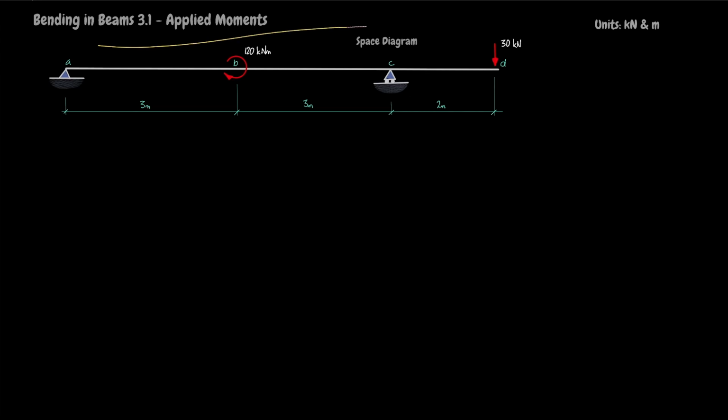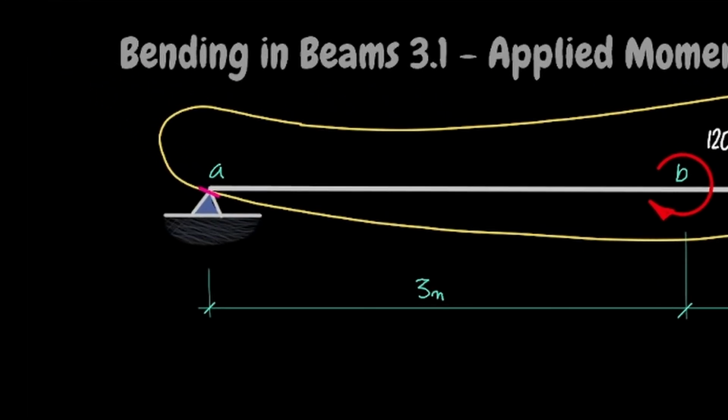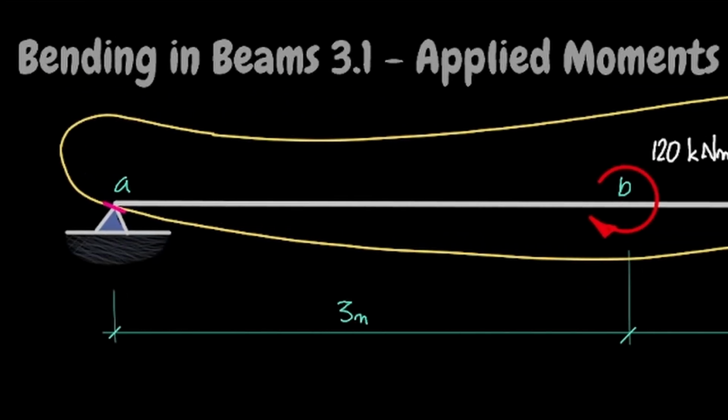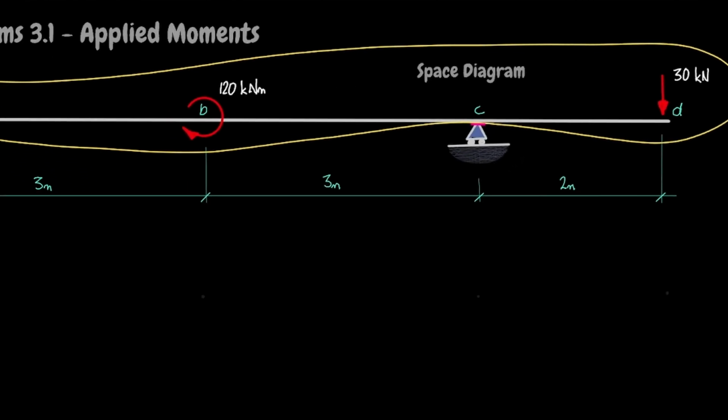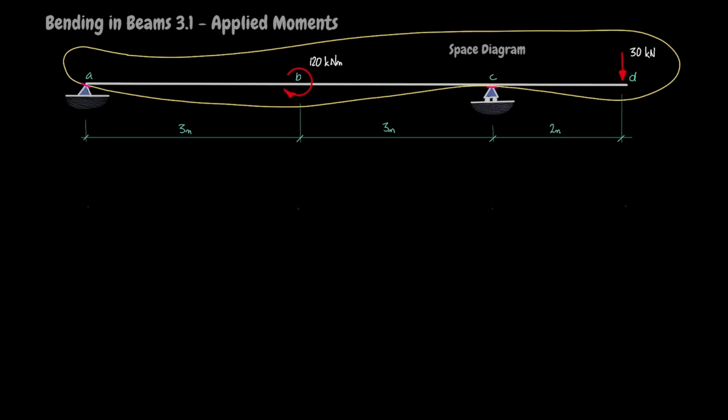Draw a free body diagram bubble that cuts the beam away from its supports. The purple lines represent cuts that will expose the unknown reactive forces. If this makes little sense to you, click the link on the screen to find out more about cuts, free body diagrams, bubbles, and all sorts of cool stuff.